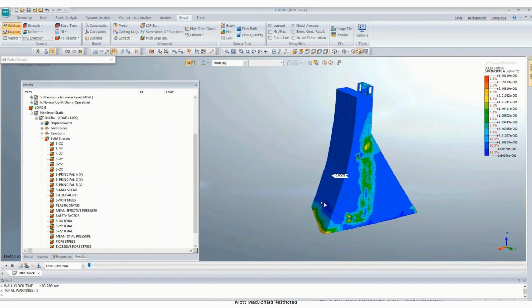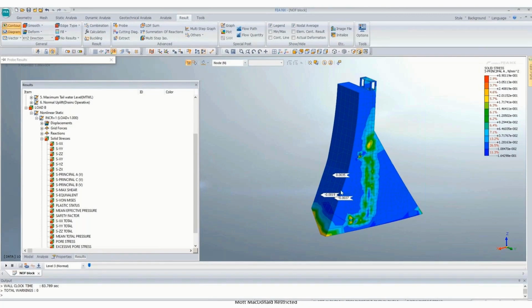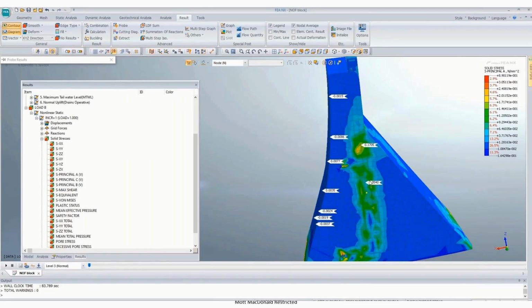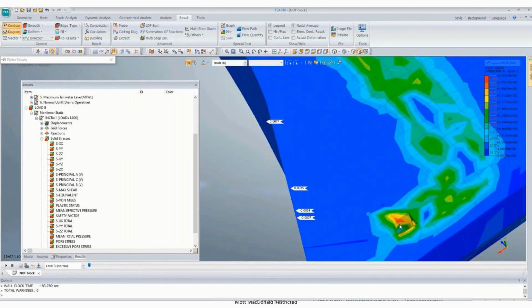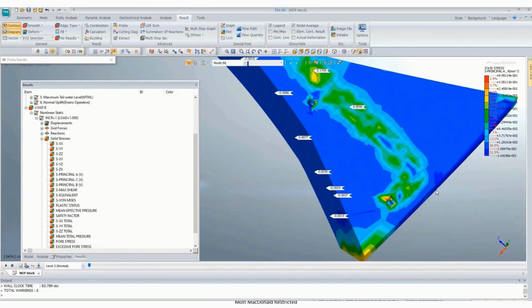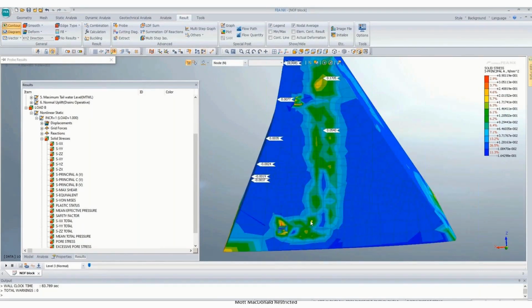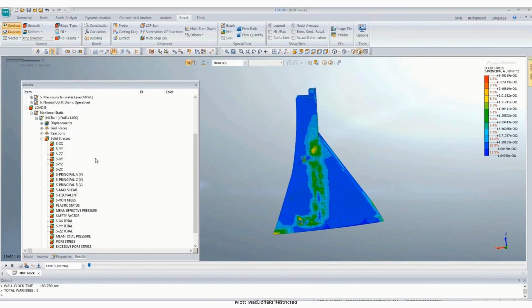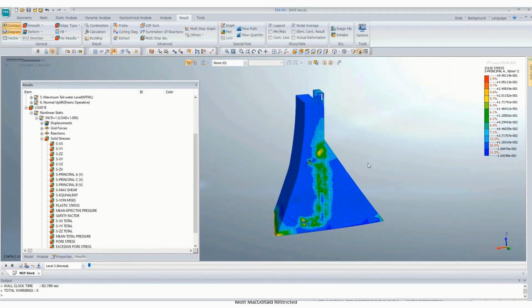We have established that our dam is stable for static conditions, so it is negative. There is slight tension, 0.0035, in some of the nodes on the upstream face. That is okay for numerical analysis, no issues with that. There is also tension in this lift well, not considerable, actually this is also not very high, so you will find red color here, at the edges. Anyways, we will be providing reinforcement in the lift well walls and stairs. And we have to analyze it separately for bending moment and shear forces, these flexural members.